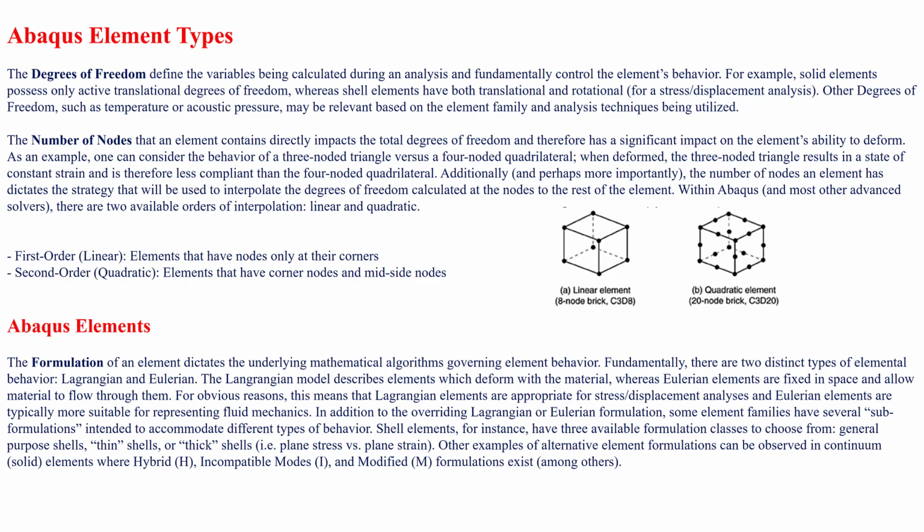Inside, we have these subdomains that we're gonna discuss later on. Again, the examples we are going to consider have been refined in the form of hybrid, incompatible modes and modified formulations. Even reduced integration and so on, so that we'll see later. Again, with respect to the requirement, like the shell elements, we have thin and thick elements, for plane stress and plane strain considerations and so on. Fine.